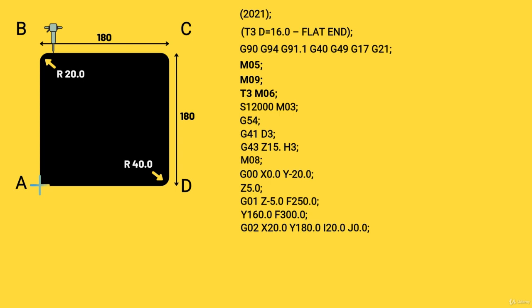Now, our next movement command is a simple straight line. So for that, we are going to use G01. We need to declare G01 here as the previous line had G02 already defined. During the first cut, we told the machine we were cutting the radial. Now, we need to tell the machine we are cutting linear again. So, we just need to give it an endpoint in the x-axis, and we don't need to tell it the y position because it assumes it's not moving in y if we don't give it a dimension.